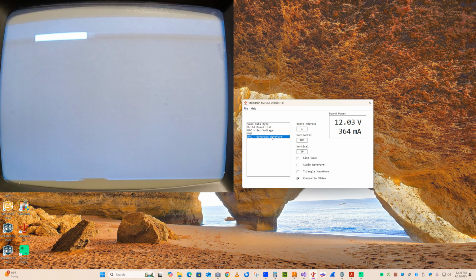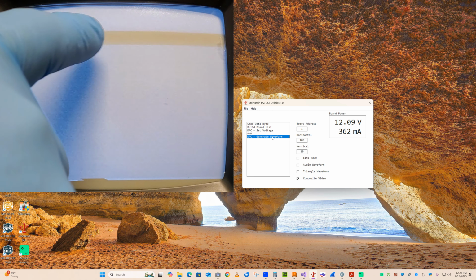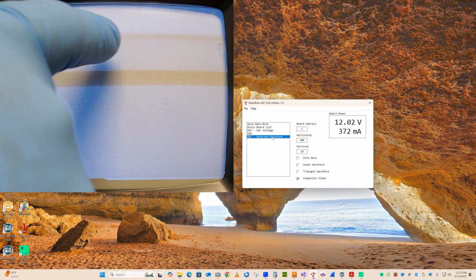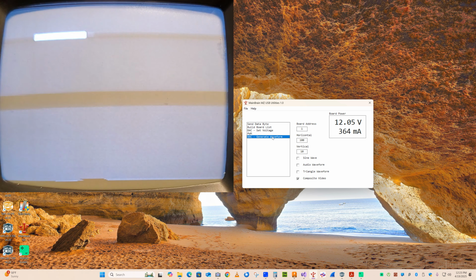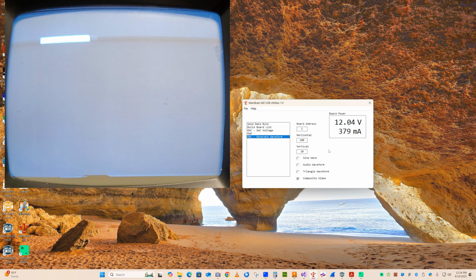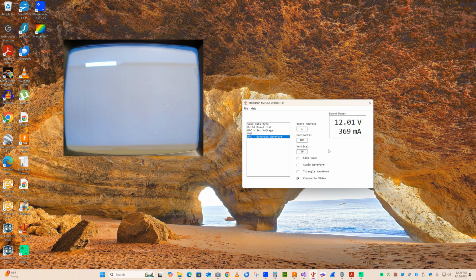But you can see down here, we have a little bit of a timing issue, and a little streak and some shadowing. That's our signal. We can clean all that up, but we're not going to do that here. This is only for test. Later, when we have a finished board, we'll write some really cool composite video code. But for right now, that's what we got, and we proved that the DAC can generate composite video. We proved that our circuit works, and we're ready to move on.